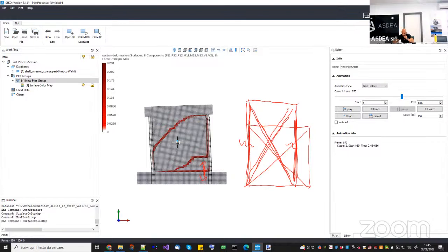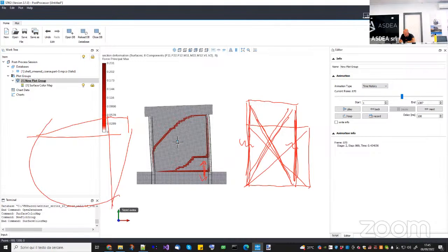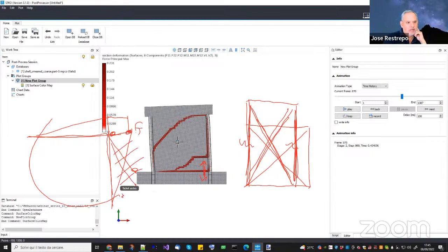In our case, you are a lot on the lower bound because of one reason. Even if you have, for example, a lot of compression, but then you load it in shear, when you're loading in shear, at least one of the principal strains is positive, and then the other is negative. Imagine you have completely damaged the tensile surface. So this one is my original surface, which was something like this, and this one the compressive one. Imagine I completely damaged the tension side, in such a way that it goes to 0. So this one is my residual surface. Whatever I have here, even if the compression is high, I'm always outside the yield surface.